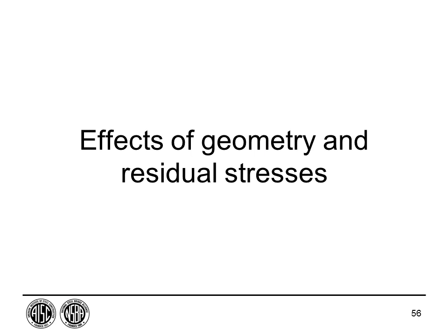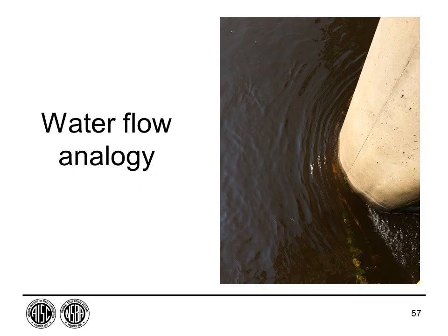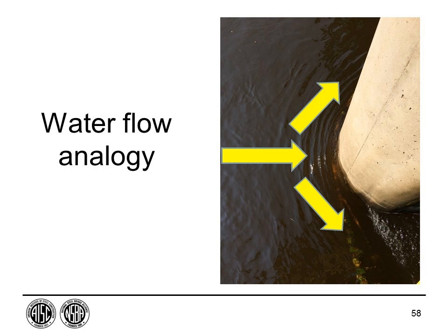I'd mentioned material, or the effects of geometry and residual stress. And these are very important, especially geometry, because it gives us insight into the likelihood of cracking. And I guess if I could, I'll illustrate it one way that would help explain things. If you can think of stress flow like water flow, you're way ahead with fatigue. You can understand a lot with how water flows.